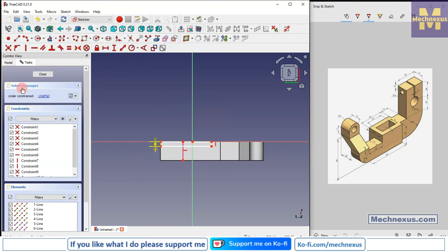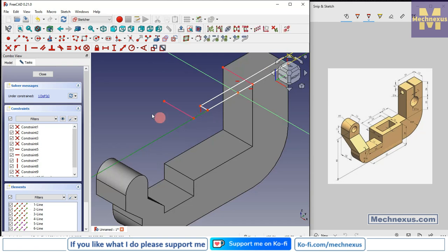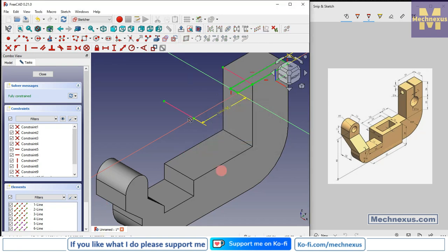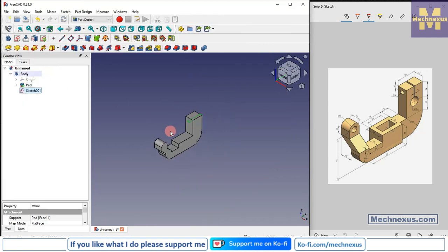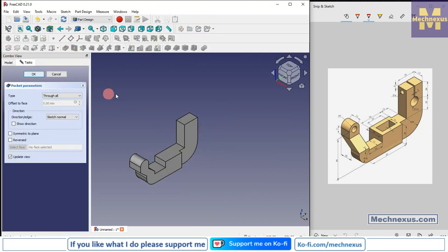Go to the model and switch to the isometric, select this edge, and now from this point to this point, horizontal dimension from this point to this point, it is 36. Now click on close. Now select the sketch, click on extrude cut, and from here say through all, say OK.